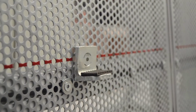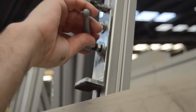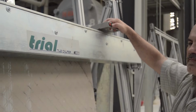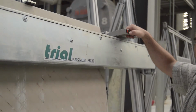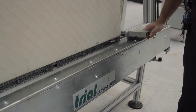To do this, we start by adjusting the mobile supports to a height and position that are comfortable for the operator. Then put the piece to measure. We set it at the top, and start measuring. Select the menu part model to measure, and click Start. We position the measuring wheel at the start of the face to be measured and press the red button. We slide alongside, and just before reaching the end, press the green button to validate the extent.